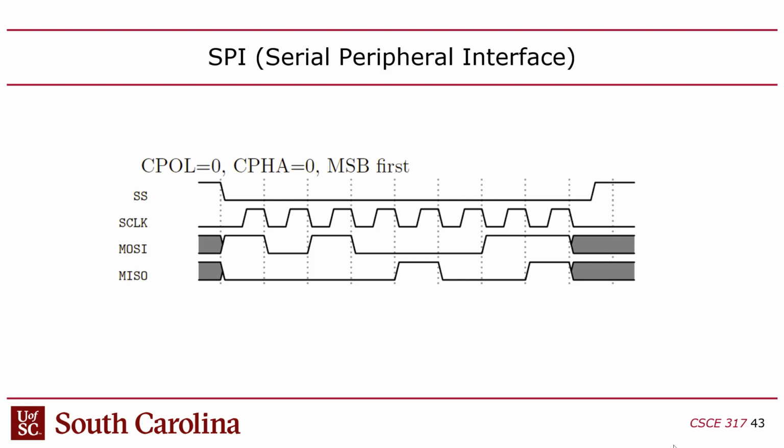Make sense? Actually, on both ends, because the receiving end is MOSI and the sending end is MISO. Does that make sense? Now, why is that important? Why is it important I know what edge of the clock? The reason is because of something called metastability.